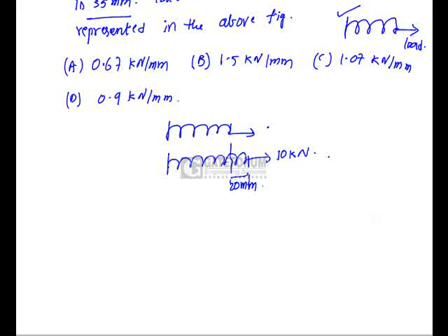In a similar way, when we apply 20 kilonewtons, the deflection is observed to be 35 mm. So here we have to calculate the stiffness K of the spring.